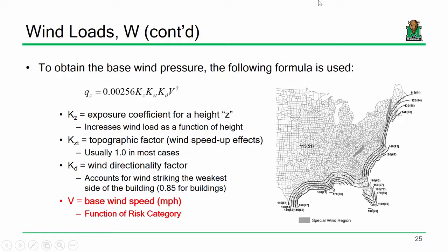Now, in some earthquake phenomena, you can get 2 to 3 G's very easily. So that's what I mean when I say it's much more of a concern with seismic than with wind. Yeah, you can have some strong forces when it comes to wind, but nothing like seismic. Is that a fair answer? And everybody else okay with that? Okay.